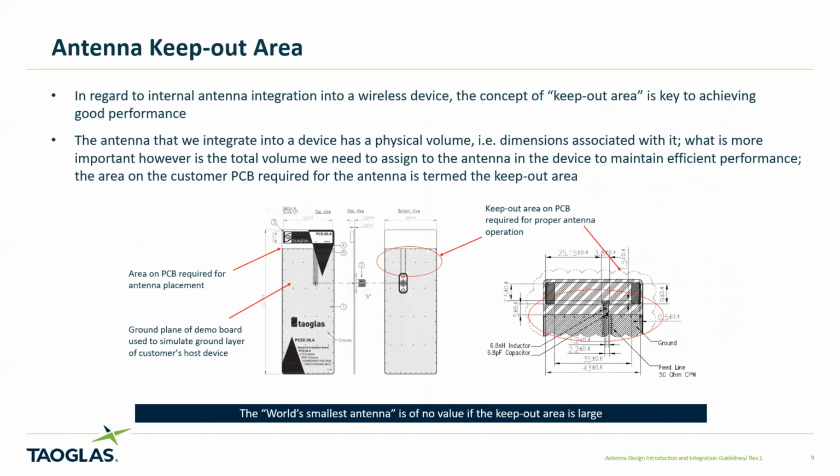That leads to the next slide, which is part of a set of slides being used now and used in the past to help educate. Really, it's not to educate antenna engineers, but to educate RF system designers, like I think a lot of the people on this call are. You're doing some RF system work, developing a radio system that's going to sit in a modest volumetric platform. When you place an antenna inside of it, not only do we need a volume or area, a landing pad, for the antenna to fit, but we also need a keep out area. Unlike a connector or a passive component, the antenna is going to radiate, so it has EM field structures emanating from the antenna element. There's a certain minimum volume, which we can relate to a minimum area, needed to allow the antenna to be positioned in a device and operate efficiently.